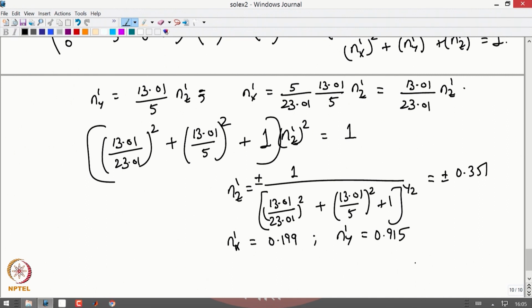Okay. So, now plus or minus for each of these cases. There are different possibilities of combinations of values, wherein I can take the plus sign for all or negative sign for all, which will represent the two opposite faces of the stress cube, wherein the stress will remain the same. So, both of them are equivalent representations of the same plane.